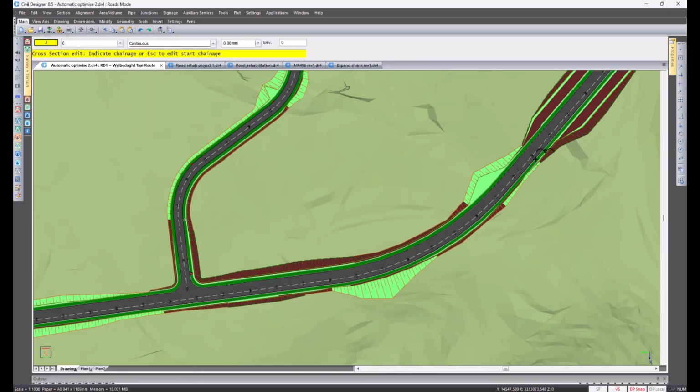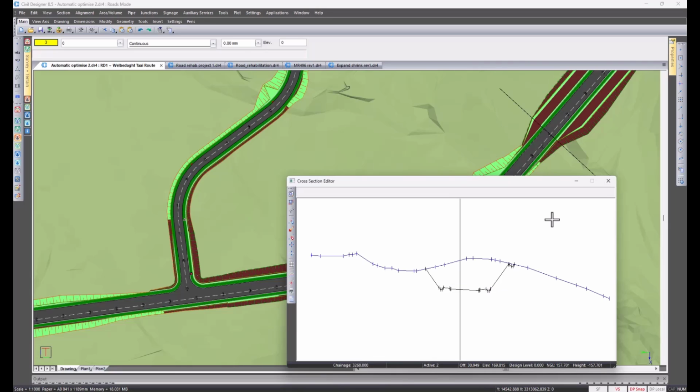We go section graphical edit. In this toolbar on the left here, you can click on this move section button, and then you can set a base layer that you're moving relative to. Click on your screen, and then you can change your design cross-section. And wherever you position it vertically, the current template at that change would be applied. Okay, so that's the optimize inside this graphical edit window.